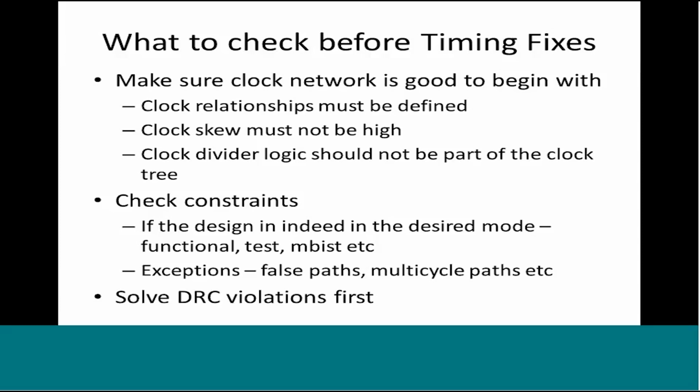You must make sure that clock relationships are well defined. The clock skew is not high, is within limits. The clock divider logic, for example, should not be part of the clock. We have just noted down some important things. This is not a complete exhaustive list, obviously. So all such cases can create issues for you.